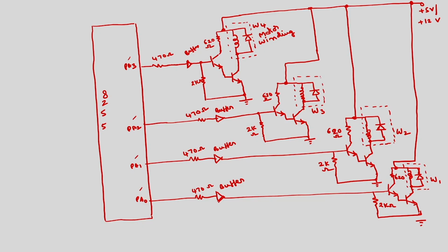Okay. If I want to write the program here, the procedure is that I want to operate this motor at a certain speed. These are the specifications. You have to first decide the specifications before writing the program. The interfacing is the same. How much delay is required between two consecutive sequences? As I have discussed, the sequences that you have to give are 0 0 1 1, then 1 0 0 1, 1 1 0 0, 0 1 1 0, 0 0 1 1. Like that you have to repeat the sequence.